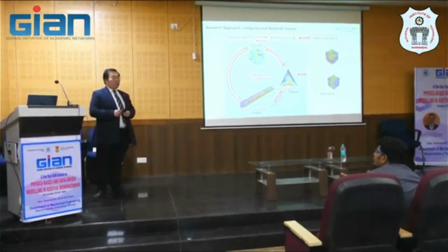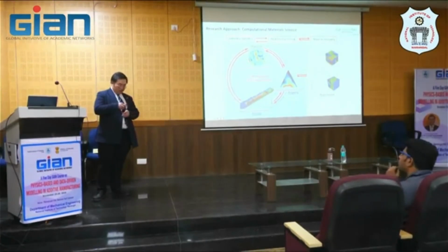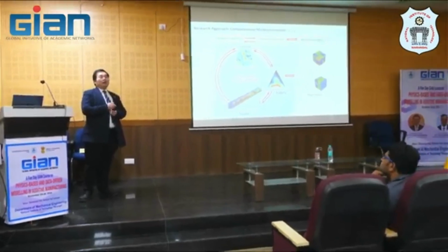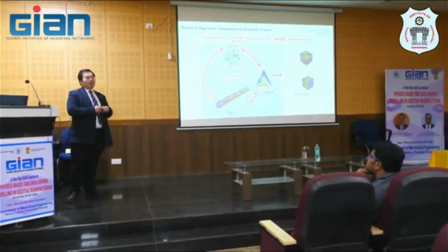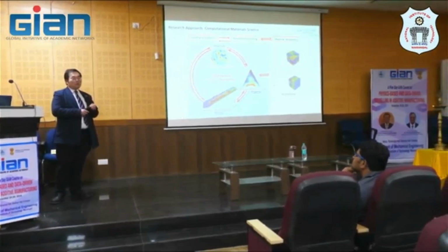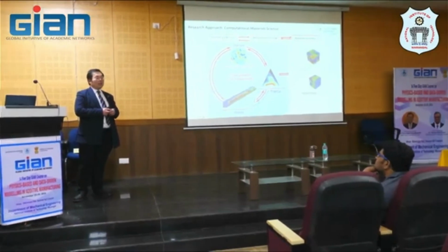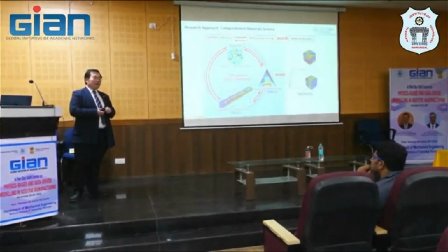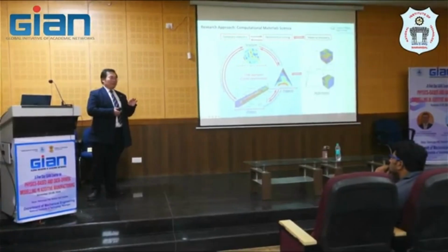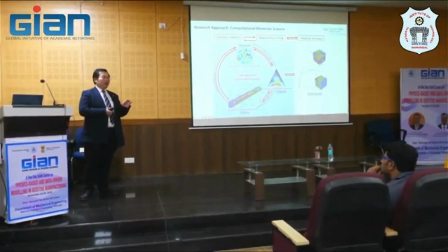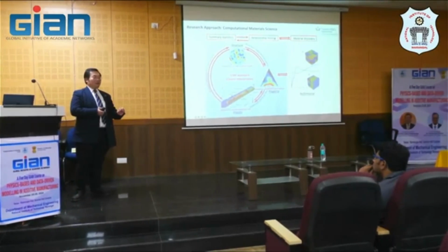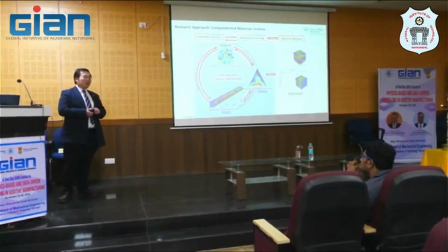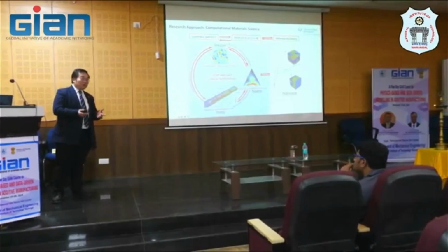You're not going to use the full maximum energy to melt your powder, because it will sputter everywhere. You need to find the optimum lowest power possible that you can melt without any defect, right? And that means the morphology contributes to defects, like lack of fusion, for example.